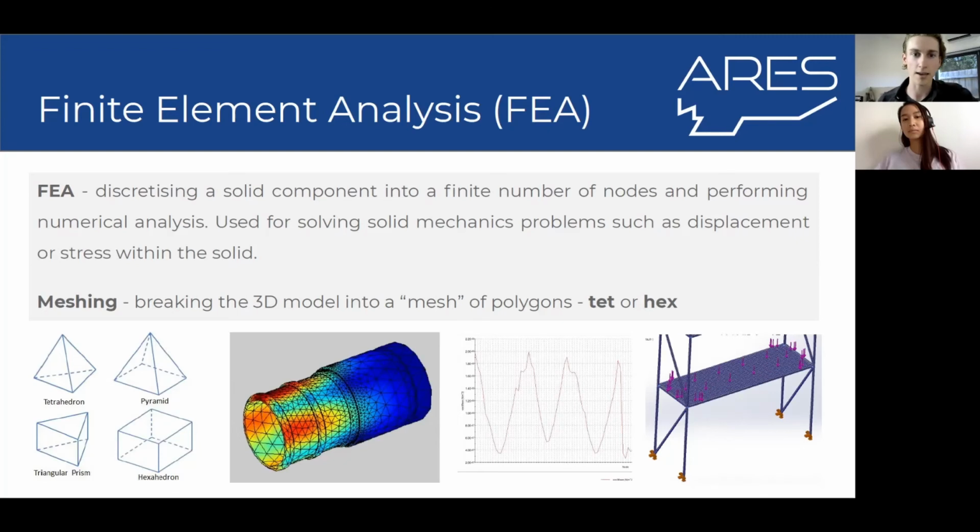You basically break your 3D model into lots of tiny little pieces and apply basic stress-strain, basic physical principles to each of those little pieces, and those then interact with each other, and it gives us an approximation of how that large 3D body is going to react to different forces, what kind of stresses we're going to get, and what kind of displacements we're going to get.